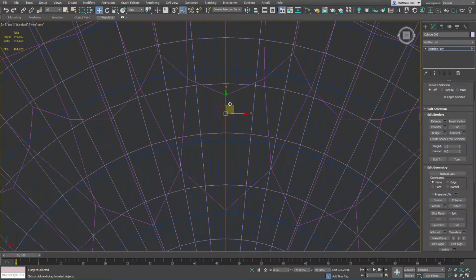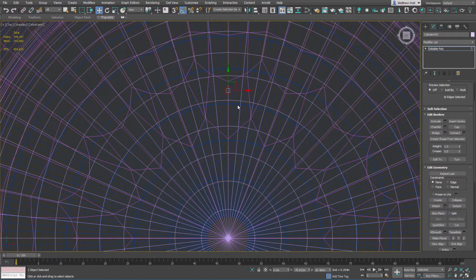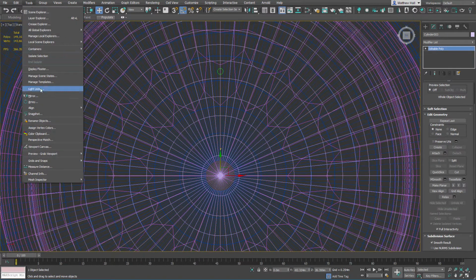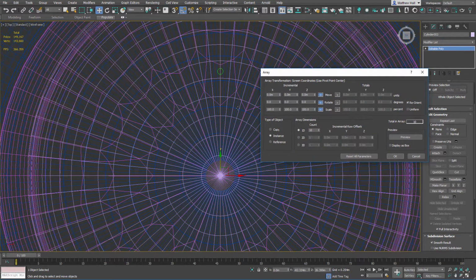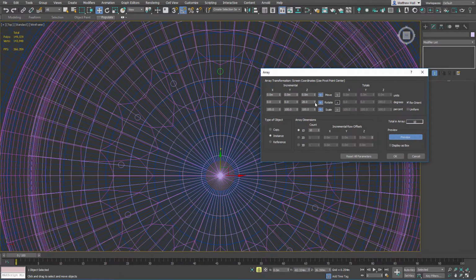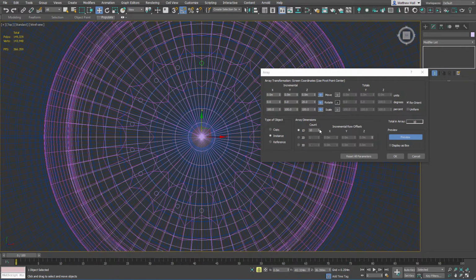So now we use our old array tool. And I don't even know how many I'm going to make here, but that's okay. So rotate, preview. There we go. Oh, good. Okay, we got a nice little, about 5. Whoa, that's probably a bit much. How many do we want total? Yeah, how about every 10 degrees? Great. And these are going to be instances and okay.